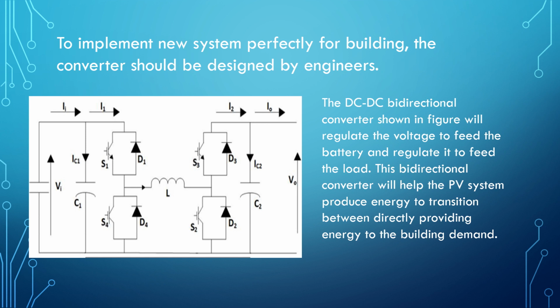Like you can see, we have the four gates, S1 to S4, and we can change the voltage to make the gate open or close. And this means the current can flow in different directions, in buck or boost mode.